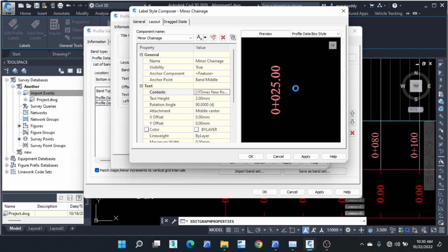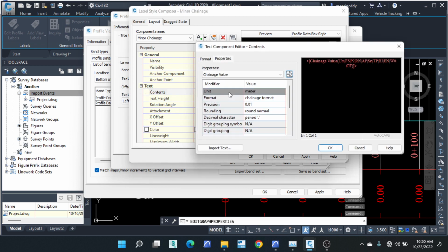And the other thing that I've seen is that we have a precision that is to the second decimal place. So we are going to remove that precision for now. So I'm going to come back to compose. Now, as you can see here, my precision is 0.01, okay? So what I'm going to do, I'm going to change this to precision 1.